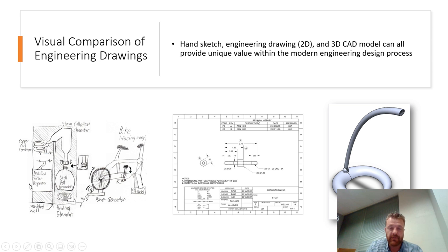You have text information contained within blocks, and then you have the drawings and dimensions. These are particularly called orthographic projections, and they're meant to provide a distortionless view of the actual dimensions of the part. That way, if someone were to give this to you and say, here's the drawing for this part, here's the actual part, is it right? You could take certain characteristic dimensions and assess the quality.